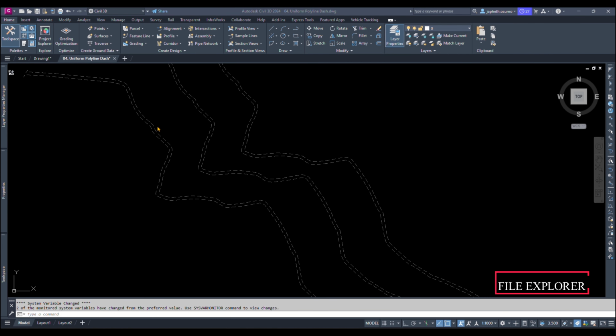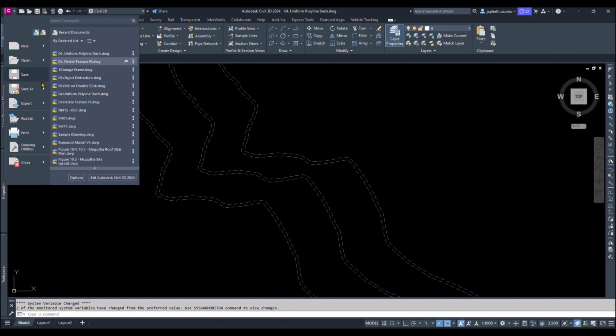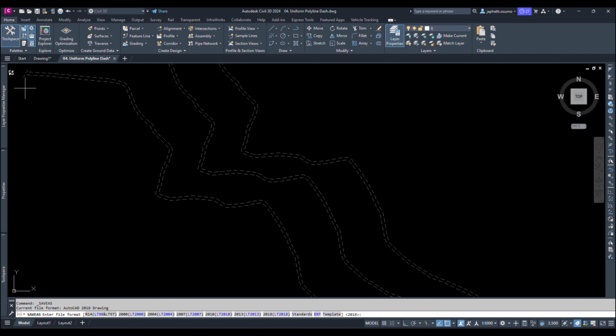Sometimes when working with very large drawings, the program can either crash or freeze, forcing one to use the Task Manager to close and restart the application. After restarting, you no longer get the file navigation dialog boxes, and instead you get a command line option, which can be relatively harder to navigate. Any attempt at saving or opening a drawing brings the command line option.